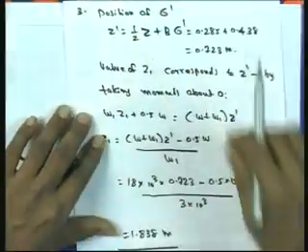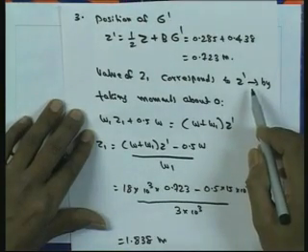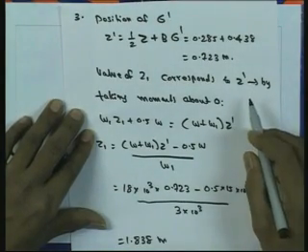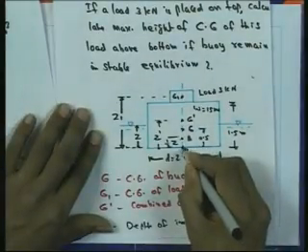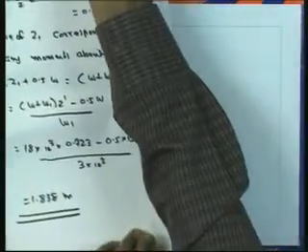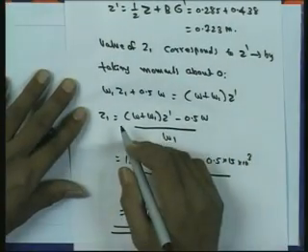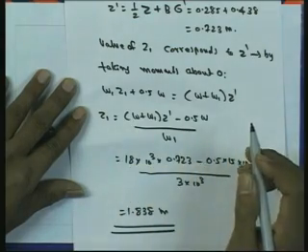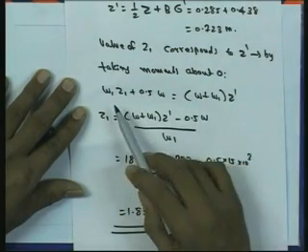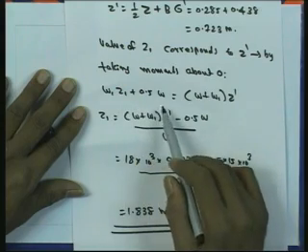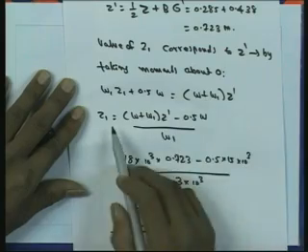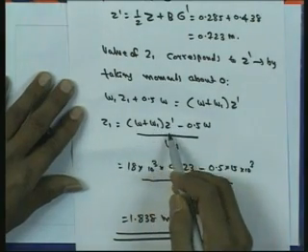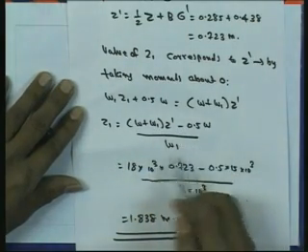With respect to the new center of gravity, we can take moments about the point O. So W1 into Z1 plus 0.5 W, where W is the weight of the buoy, is equal to W plus W1 into Z dash. So Z1 finally we get as W plus W1 into Z dash minus 0.5 W, divided by W1.